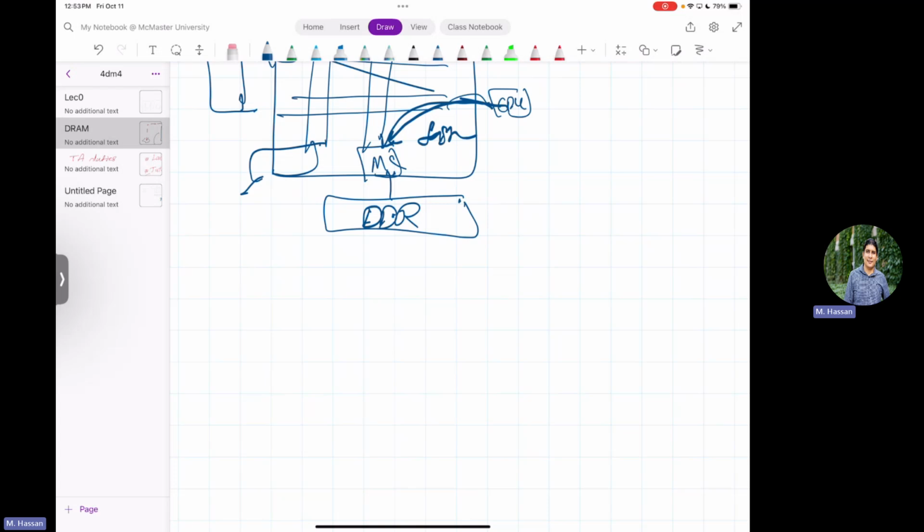It just gets an address, and you need to translate this into what row and column and bank and rank I want to access. This is called address translation. Who does this address translation? It's the memory controller, right?